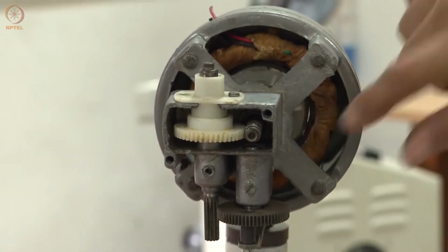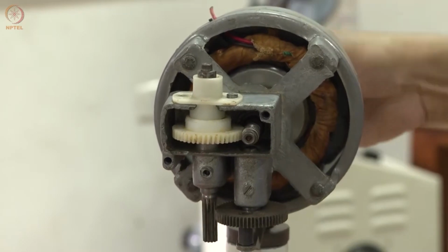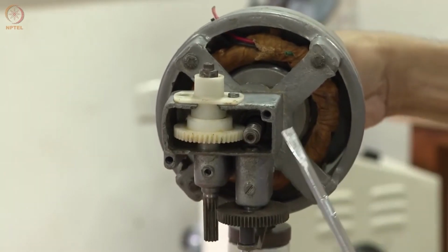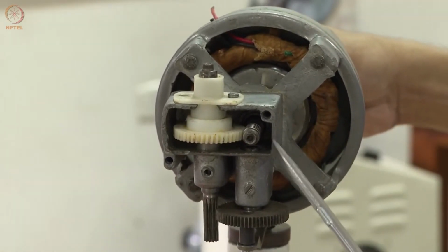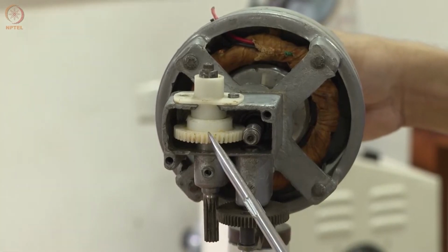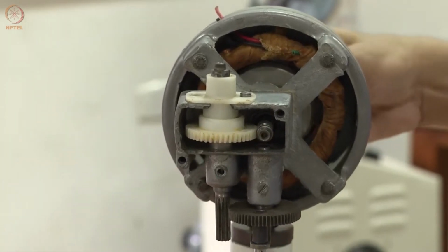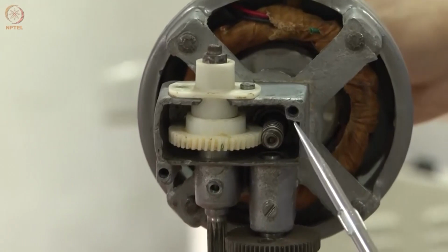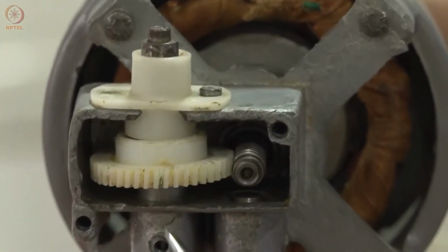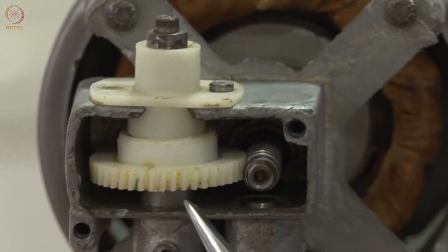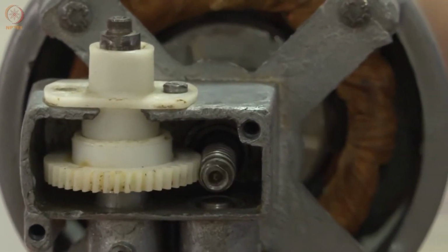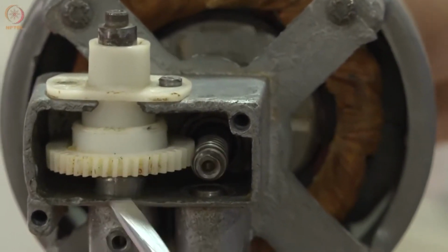The main motor, you can see I'm basically rotating. You can see it has what we call a worm, WORM, worm, and this is called a worm wheel. Whenever the fan is switched on, the worm engages the worm wheel, and as you can see, this is rotating. Now the oscillation mechanism is not engaged, so it is disengaged now.